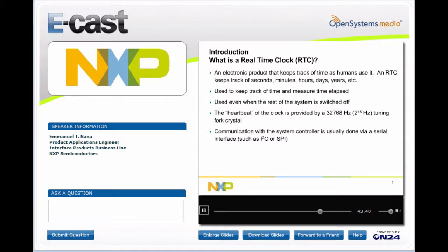So sometimes in the application, the user may want to go into a very low power mode where they disable that clock output buffer so that it's not toggling and consuming additional power. And that's the reason for the output enable feature there.